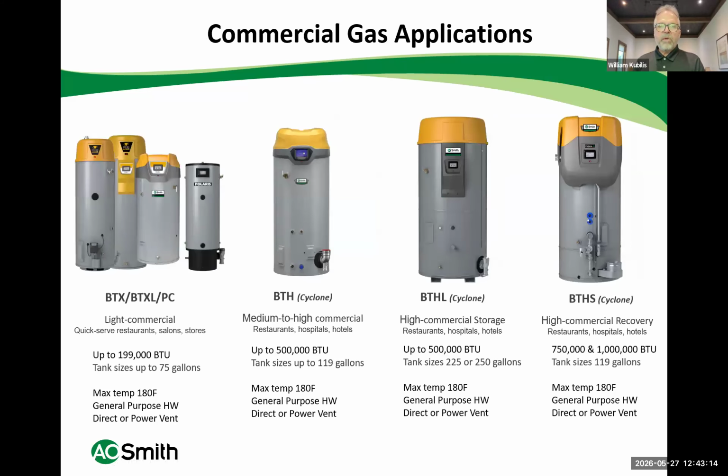So with our gas water heaters, there is quite a variety of different size water heaters, but I'll focus on the cyclones. They seem to be our most common for restaurants. They are medium to high commercial type usage, up to 500,000 BTUs. And we do have these available in sizes from 60 gallons to 119 gallons. So they're again for general purpose hot water for water usage up to 180 degrees.